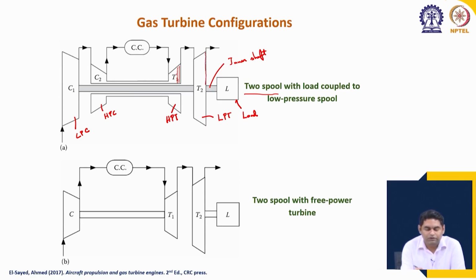Okay, so as a result they can rotate at higher speed. If they rotate at higher speed, the rotational velocity is high, so the blade velocity also is high. So more changes can be accommodated in a stage, and more work output per stage will be the output.